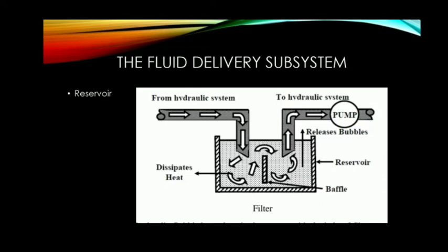The hydraulic fluid is kept clean in the system with the help of filters and strainers. They remove minute particles from the fluid, which can cause blocking of the orifices of servo valves or cause jamming of spools.